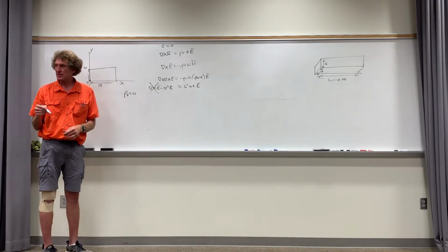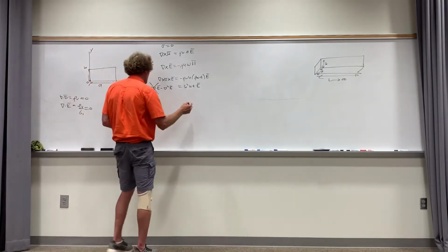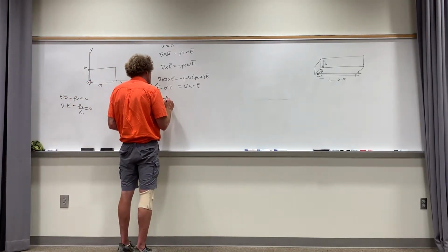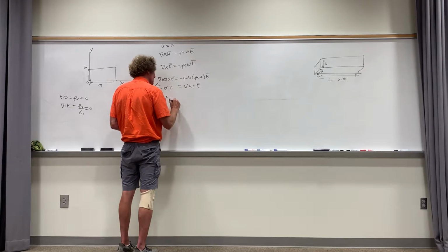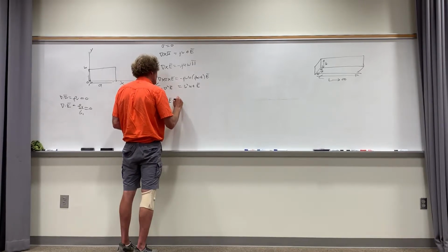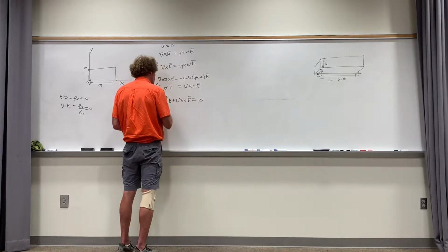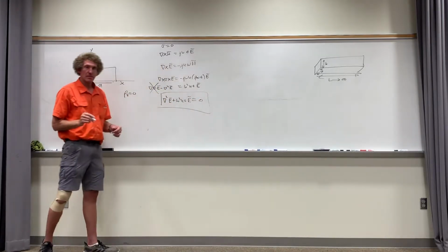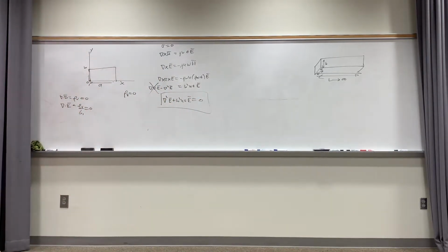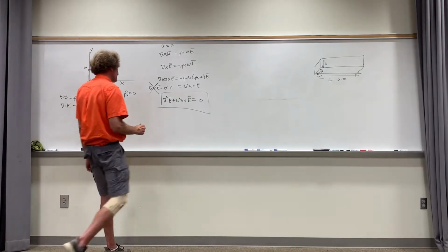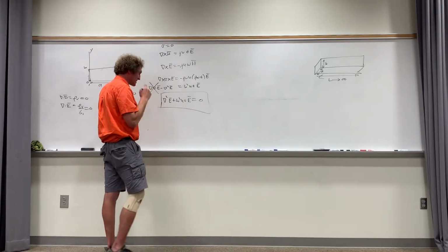This is a simplification factor, which brings me to the point where I was with the waves in free space. Now I get this equation. It's going to be that plus omega squared mu epsilon E equals 0. You can write that one down. That's the equation we solve in waveguides, and we do it in Cartesian coordinates for rectangular guides, cylindrical coordinates for cylindrical guides.